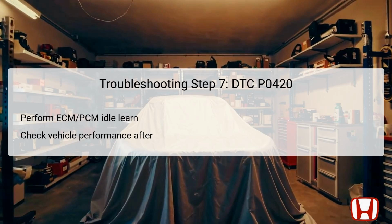The idle learn process typically involves letting the engine warm up to its operational temperature, followed by allowing the engine to idle without load for a certain period. Following this step, take the vehicle for a test drive for approximately 10 minutes while varying the speeds.